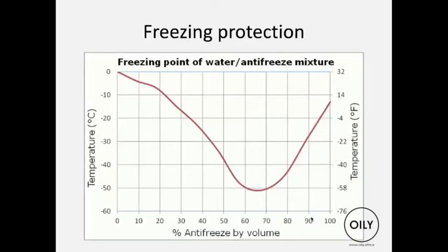Freezing protection, you can see here, the freezing point of water and an antifreeze mixture. Pure water is 0 on the bottom here. It freezes at 0. Maximum protection is about 65% antifreeze. You will go down to -50. We don't need -50 in South Africa. So we usually run about 40%, which gives us -25.